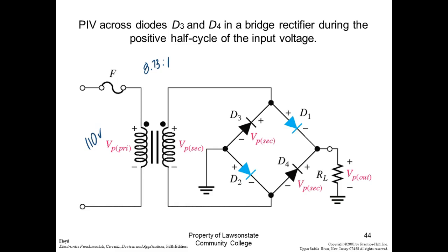And if it's rated, if you have the ratio, then normally you can reverse the primary and secondary. If they give you the voltage, though, you pretty much have to leave it because of the thickness of the insulation. That makes sense. So normally we wouldn't use this for a step-up transformer because if I put 110 volts on the secondary, I would get over 800 volts out of the primary, and the insulation on the wire probably wouldn't handle it.